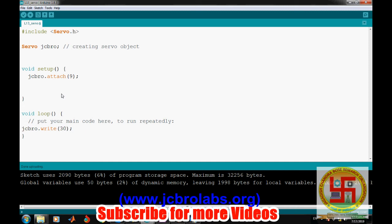So we need to start the serial port, Serial dot begin at a rate of 9600, and then we will create a for loop. Because we are reading the data, we need to create a variable as well, so let's say int angle.